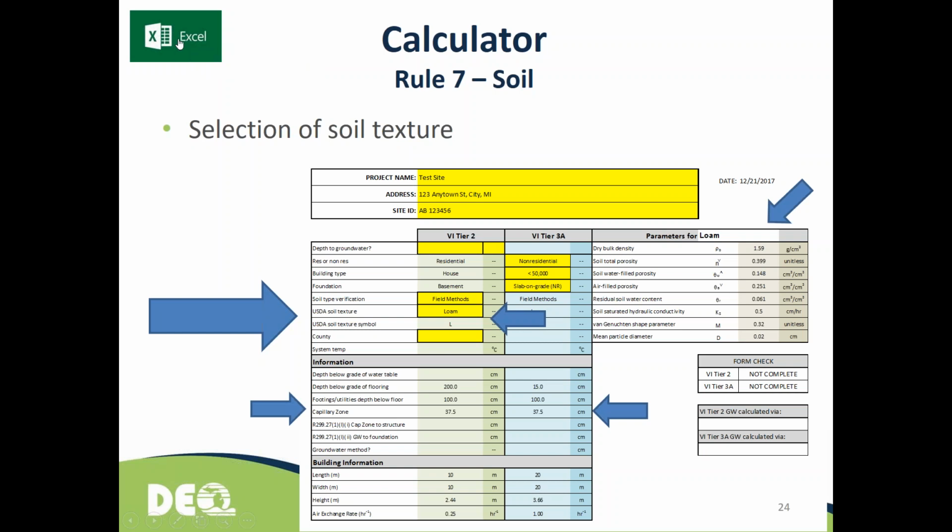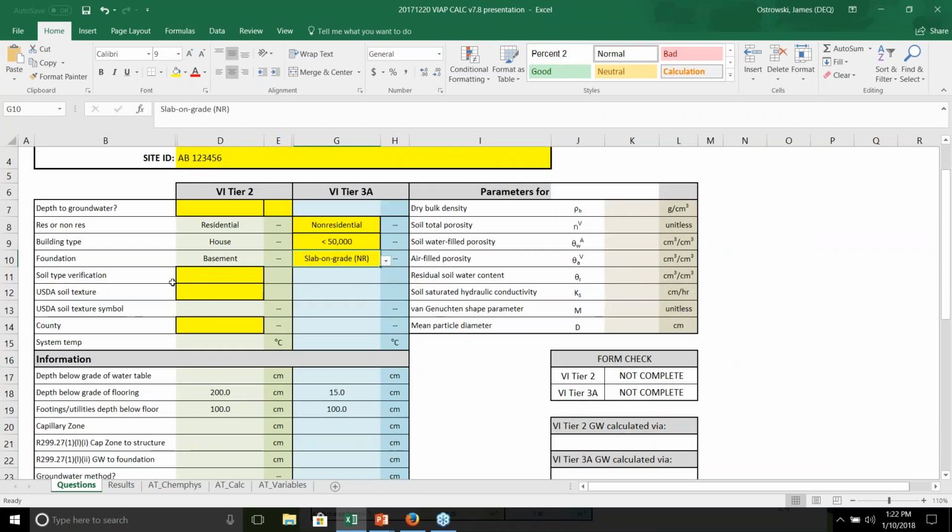So looking at how this works and self-populates, again, soil type verification, when we know that we have those 5 methods, the 3 that we can do out in the field are right here. If you look at IV and V, those are for other materials for beneficial use as well as condition for bedrock. So those wouldn't apply here. But you could always use unknown to get that. But if we select unknown, you can see that we get a choice of 1 soil type, where if we choose the field methods that we talked about, the approved field methods, you would get the choice of 4.